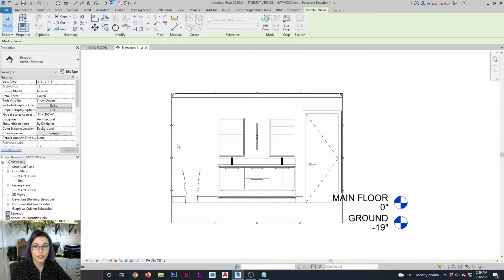Now, different interior designers treat this differently. Some of them do not show thickness of floors, ceilings, walls at all. I like to show them because sometimes I will be using the thickness of my walls, for example, to introduce additional detailing. Think of things like, for example, when you have a deep-set window that you're building a seat onto, or imagine a niche in your walls for display or for your shower, those kinds of detailings. So I like to show my thickness of wall when possible, and it also creates this very nice thick rectangle that encapsulates everything very nicely.